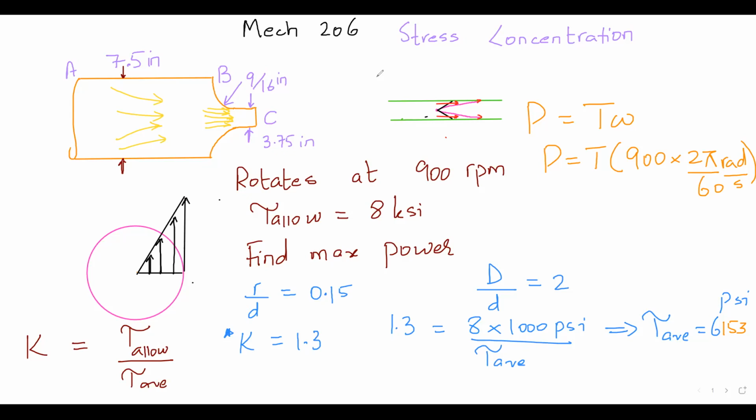My point is that every shear stress that you are finding using Tc over J, or IP, gives me an average estimate. Exactly like for the class, the average comes out to be 65. But there's somebody sitting who has a score of 95, who is completely out there. I have to take into account him. So this K value gives me that kind of compensation, where I also take into account that one individual line that is exceeding my expectation of that average shear stress.